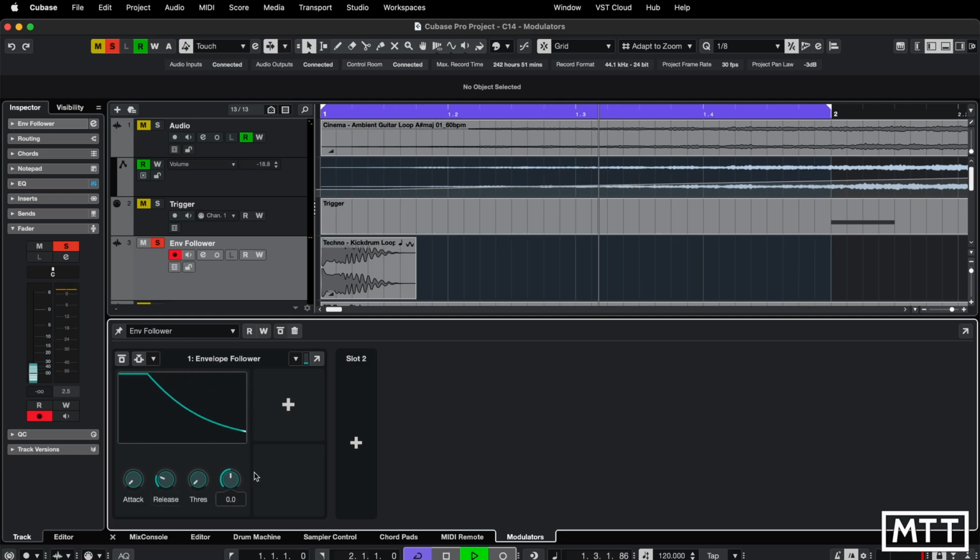Now, the threshold and gain controls, these are kind of interlinked. So what we're going to do is bring down the release so it's a little bit quicker without it being glitchy. And these work kind of in concert with each other. If you bring down the gain, we can see the level here is actually reflecting this more closely. If it's at the normal level, it's saturating the output completely and we're not getting that little drop in level. Whereas if you bring this down, you can see if we get it to the right kind of level, it's reflecting the fact that this gets louder, although probably not quite as much as that. If we whack it all the way up, we've got loads of level there.